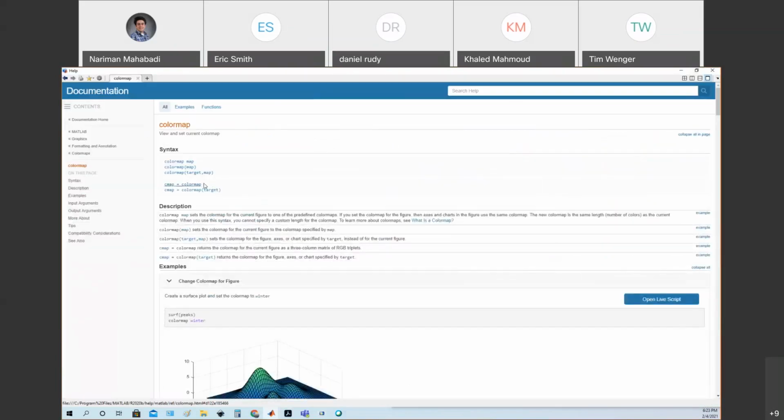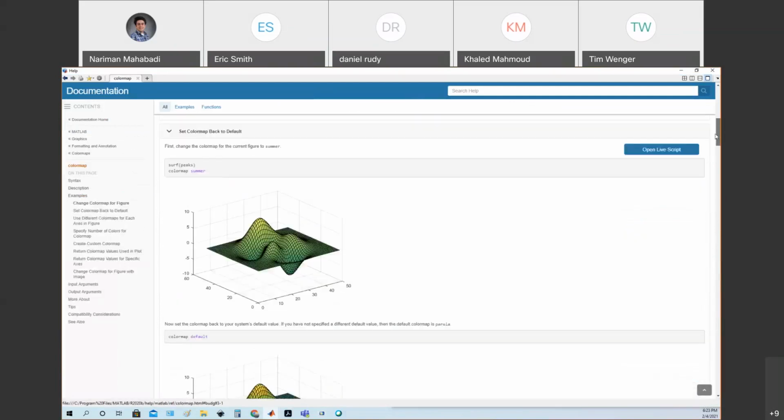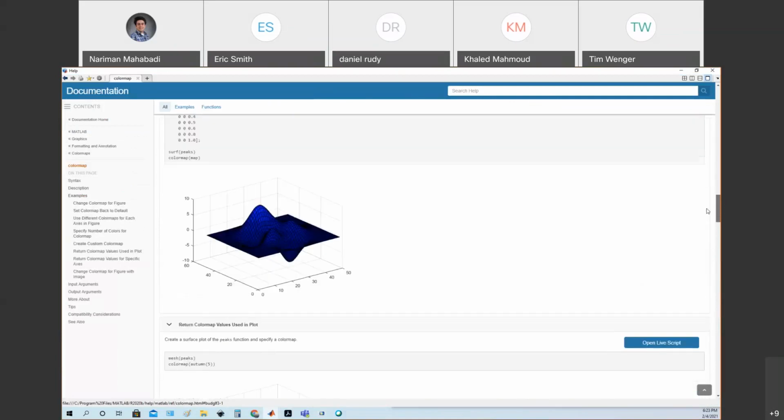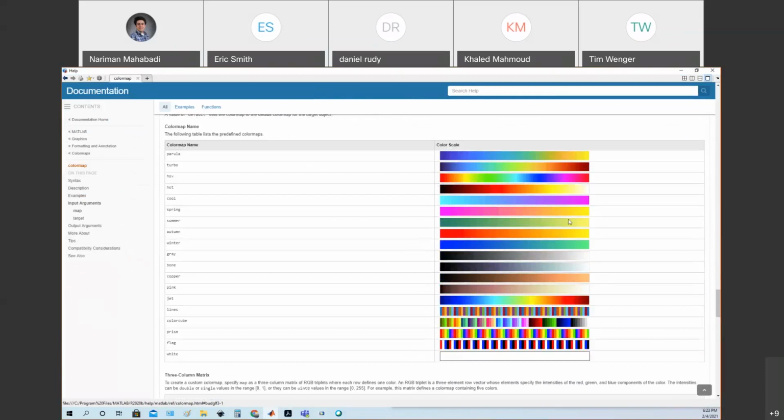So this is just talking about the color maps, because you can change the frequency of the colors, or the value of the colors that you are using in your contour F. If you go to the bottom, you can see the different options. For example, in thermal conductivity type of problems, for advection diffusion problem for temperature, we're going to use the hot system.